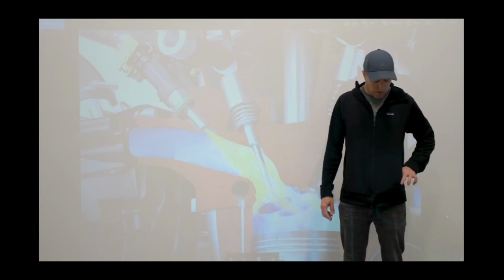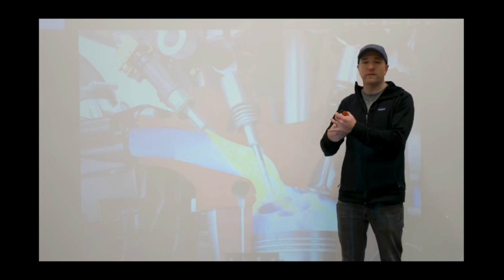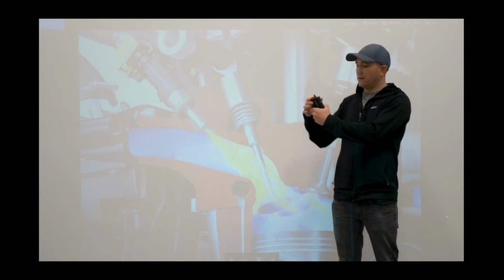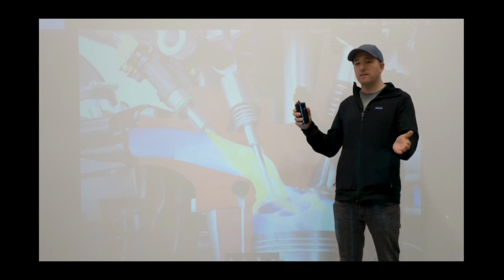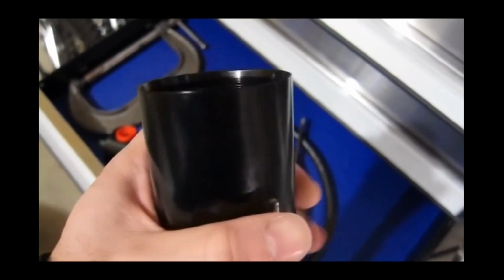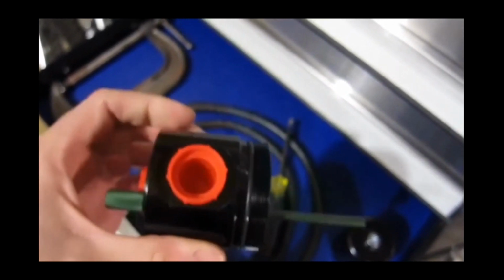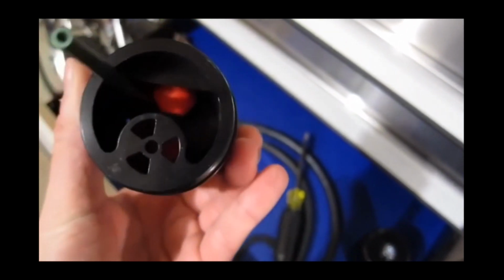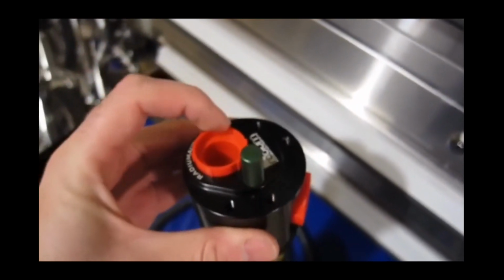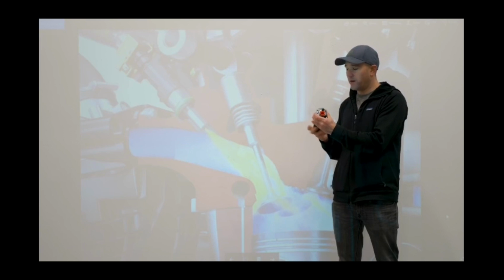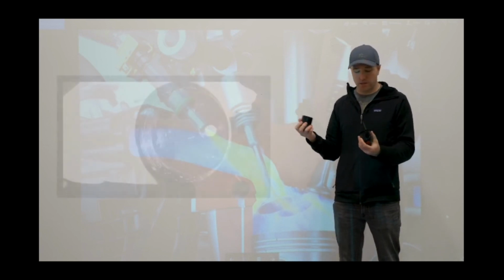The first thing is oil catch cans, something like this Radium can. And it doesn't matter what brand you use. Basically what this does is it runs in between the PCV valve and the intake manifold. And what it's designed to do is to catch and separate the oil and unburned fuel and send back clean air that's filtered back into the intake manifold so you don't get the sludge. And the nice thing about these catch cans is if you get a good one, you can catch the oil and drain it. You just drain it every time you change the oil.